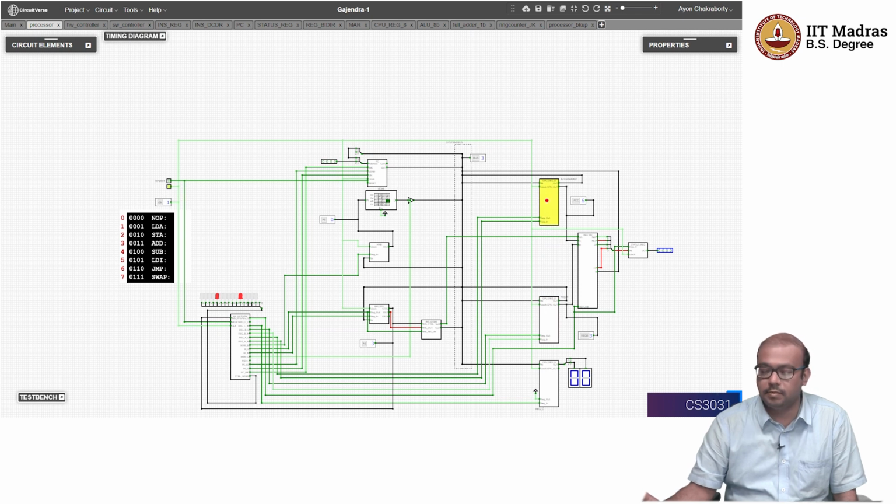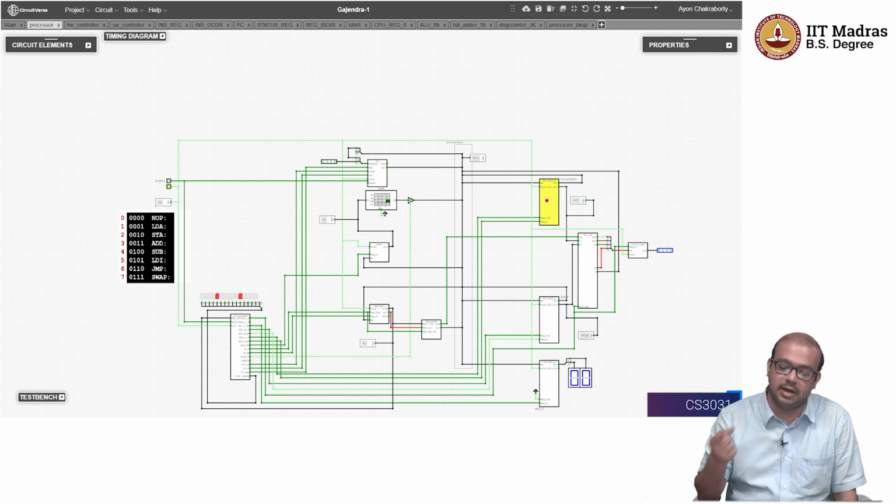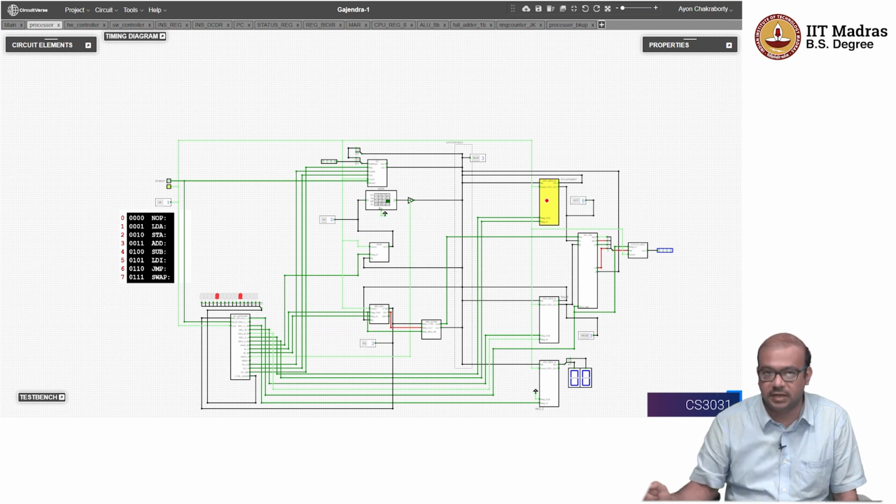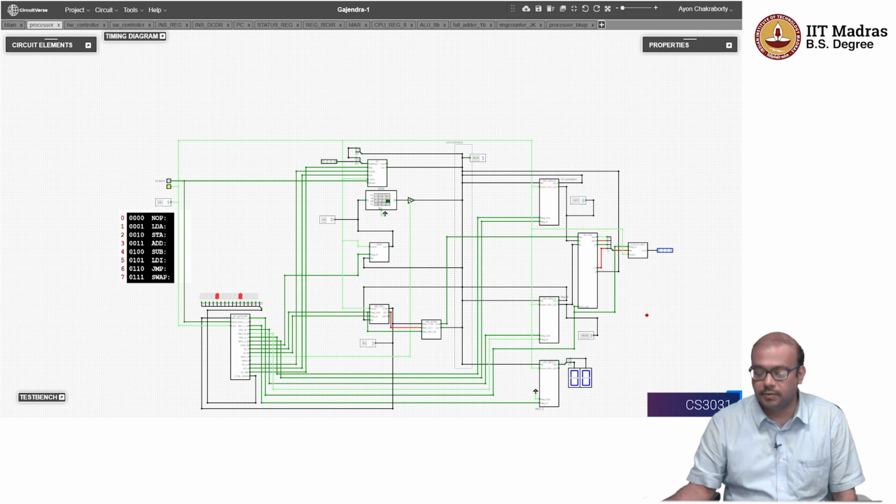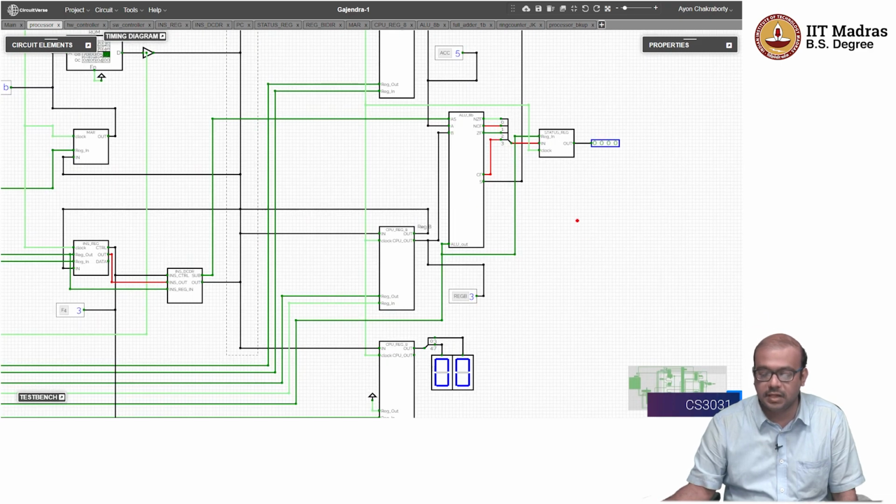So the ALU, I can assume that it contains the value 8 now, because it is a combinational circuit. So in the next clock pulse, what the controller will do, the ALU will be given the ticket to write the data in the bus, and register A is going to read that. Okay, so if I give a clock pulse, 8 is going to come out to the bus and will be written to where? It will be written to register A. So very clearly the game is now just here.